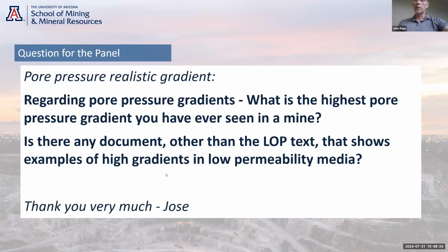It's a good diagnostic tool. You can take a look at vertical gradients, and it can tell you a little bit about what's going on. Like Jeff's absolutely right, where you have flow barriers or singularities of some type, recharge, that kind of thing, you can get very, very strong gradients. But in a natural system, if you see the unit gradient, then you know you have some kind of vertical layering, or maybe you're in the vadose zone as you approach the unit gradient of 1. And if you see fairly low vertical gradients, then you know you're in a lateral flow system. So you can use it as a bit of a diagnostic tool.